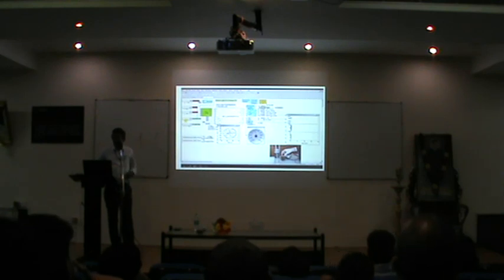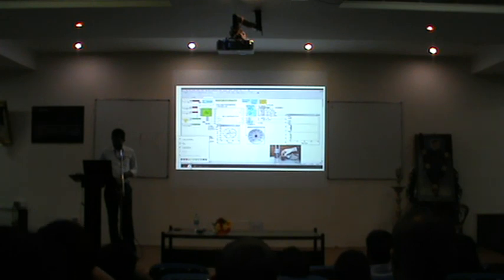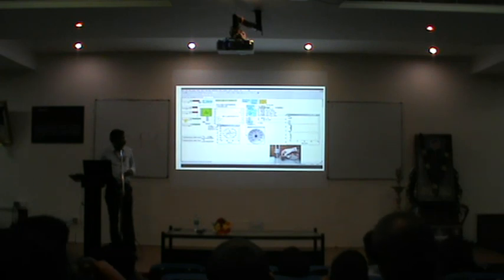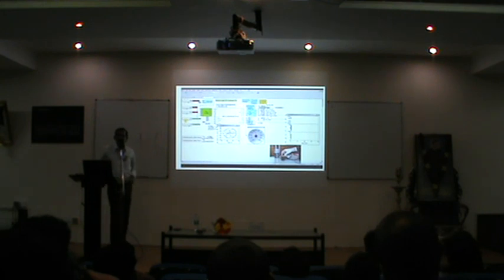You see this? This is a kind of HIL module which I was talking about, the hardware-in-loop simulation module that you see here. The actual hardware is here. Some of the control information is going from the screen, some of the control information, not all of them. Feedback plus the output, all those things are obtained from the hardware. The program is running on the target device. It is not very clearly visible here, but you see a red colored thing there, that is actually a development board. The program is getting executed from there.